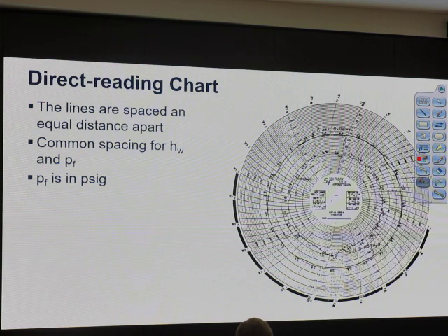Then they slowly developed integrators, where the individual would place the chart on a round rotary table like an old record player, run a needle across the top of the chart and trace it, and it would calculate the rate at each of those hour points and add them up to give you your 24-hour day rate.